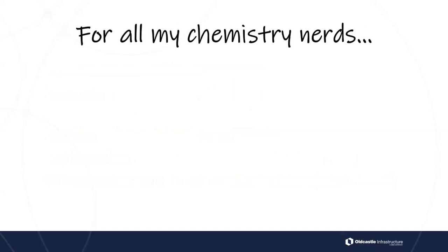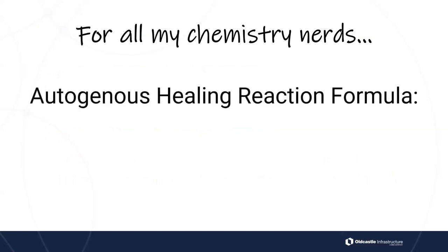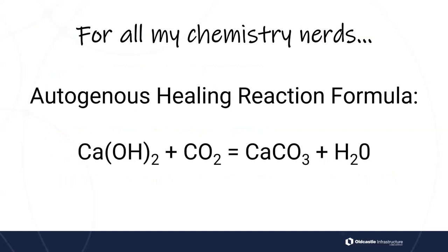Okay, so I know there's some people out there that are chemistry nerds like me. I love chemistry. I'm fascinated by it. So I'm going to share with you the autogenous healing reaction formula. So this is the formula here. As we can tell, this is the calcium hydroxide. When it combines with the carbon dioxide, right? The result in the formula is we've got this calcium carbonate, CaCO3, and water. That is what results in this chemical formula.